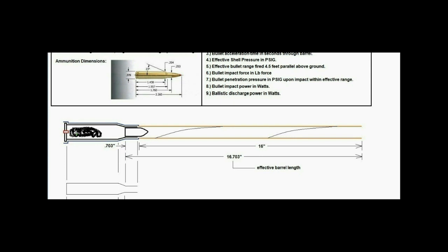And so the ratio between 1 gram of smokeless gunpowder mass to gas production is 1 gram of smokeless gunpowder will convert into 342 cubic inches of gas. So you can imagine the amount of pressure that builds up in the effective shell volume, which is the cylindrical volume including the conical taper volume, which induces a dynamic pressure spike as well.